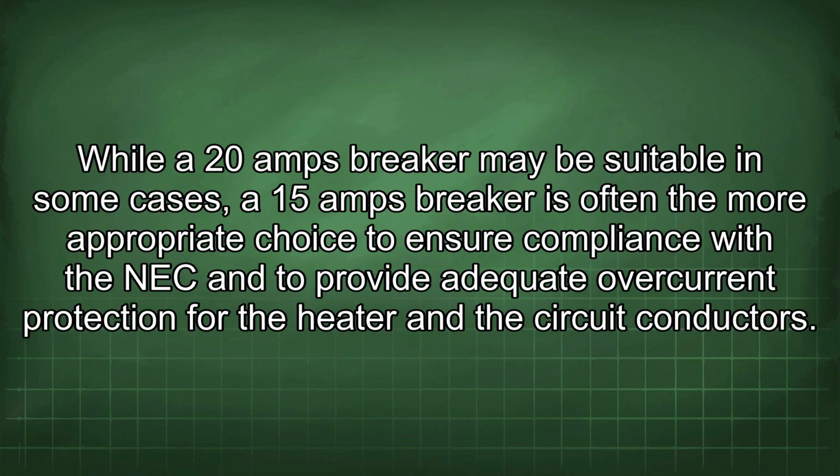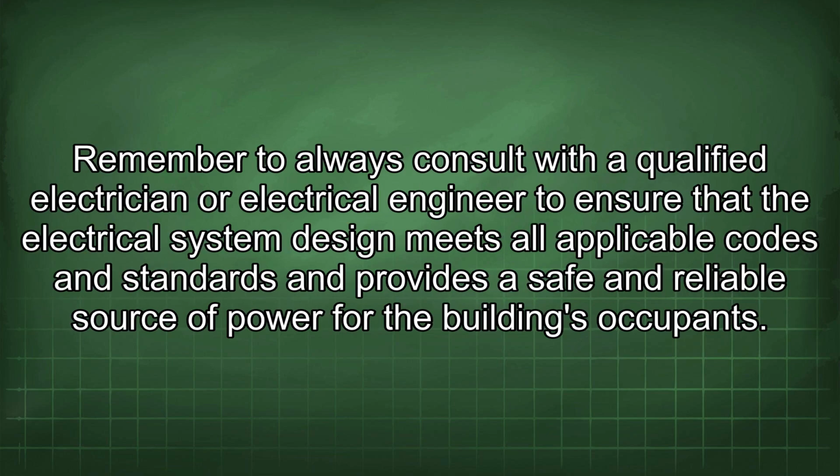While a 20 amps breaker may be suitable in some cases, a 15 amps breaker is often the more appropriate choice to ensure compliance with the NEC and to provide adequate overcurrent protection for the heater and the circuit conductors. Remember to always consult with a qualified electrician or electrical engineer to ensure that the electrical system design meets all applicable codes and standards and provides a safe and reliable source of power for the building's occupants.